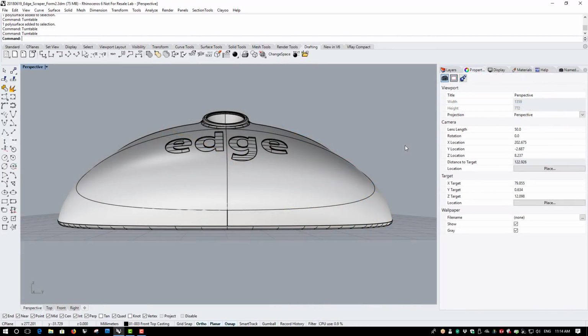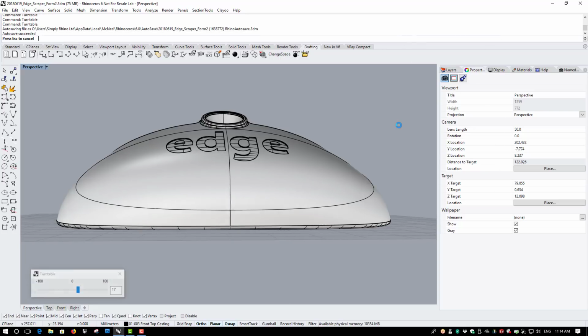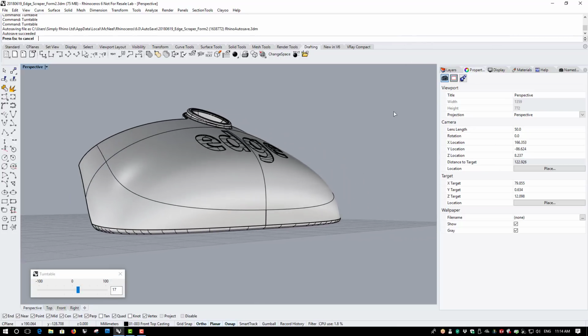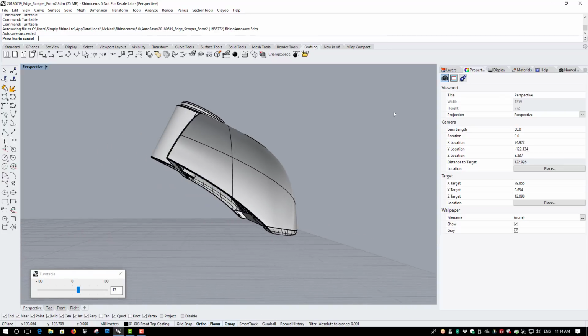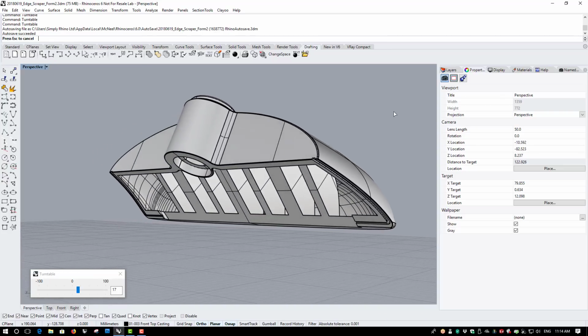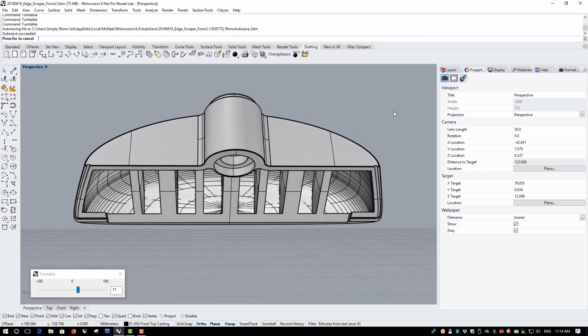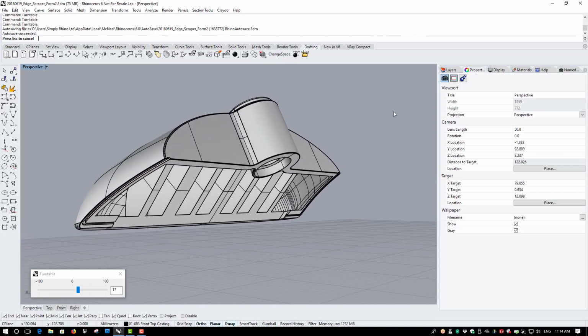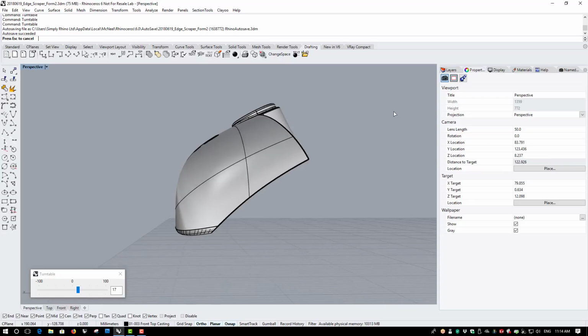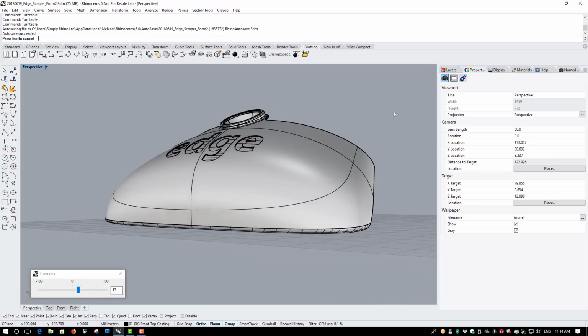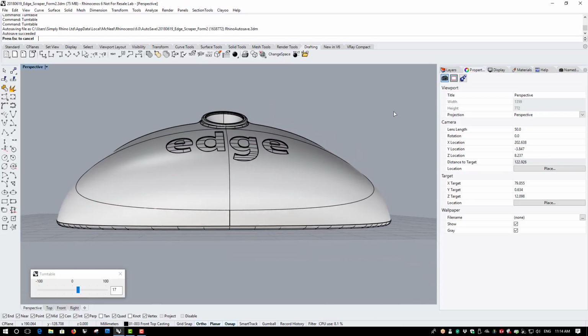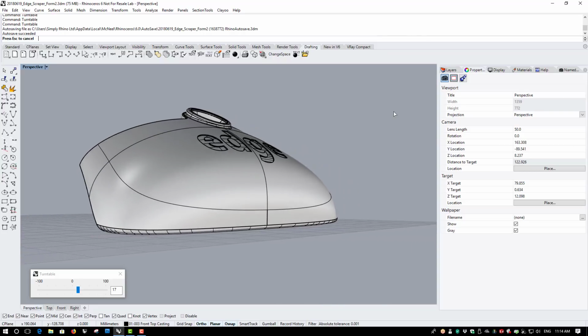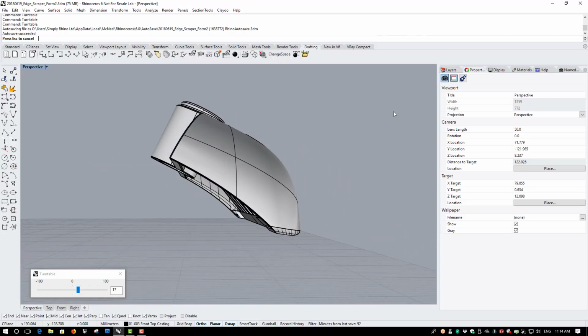In order to generate a valid STL file, the Rhino geometry for each component must be a closed volume, otherwise known as a manifold solid. What we mean by this definition is this: the outer surface or shell of the component that may be comprised of a number of joined surfaces must have no gaps or open edges between those constituent surface edges. Therefore, the outer surface describes a continuous shell creating a watertight volume.